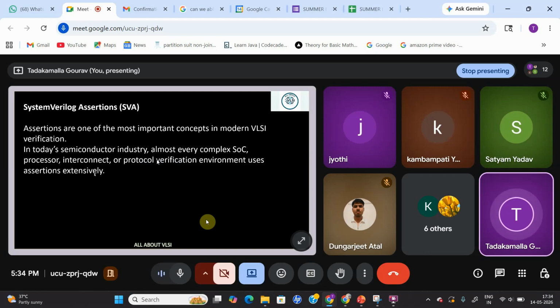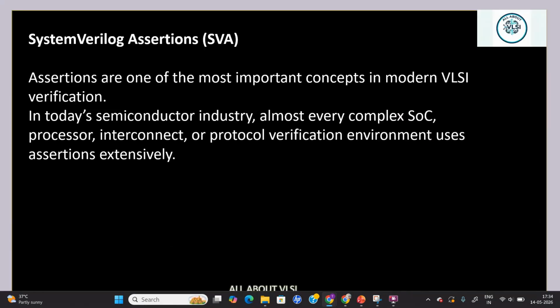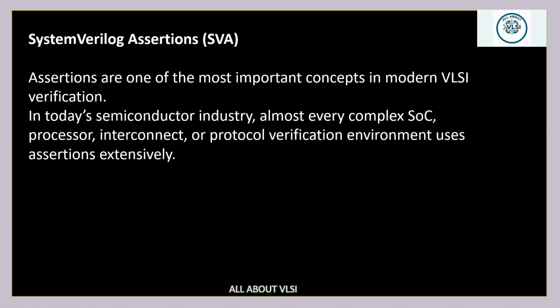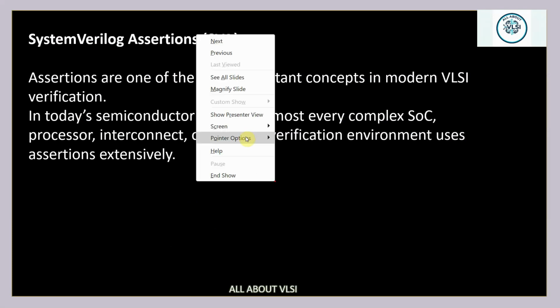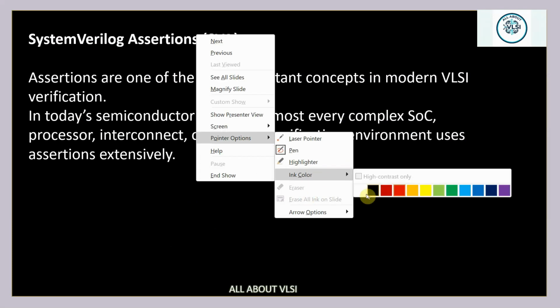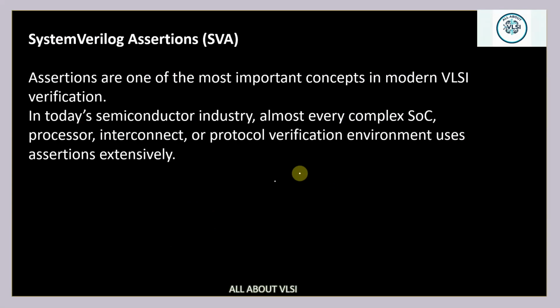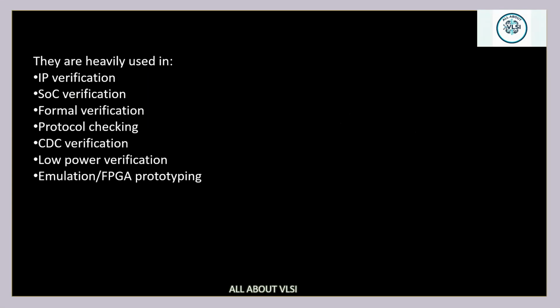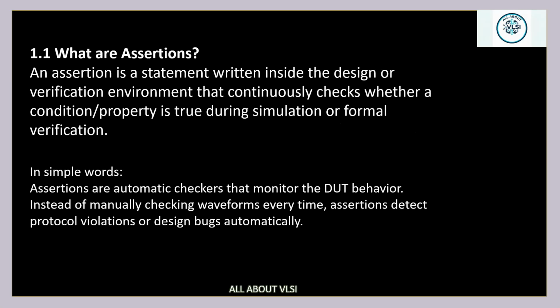Now, coming to SystemVerilog Assertions. Basically, assertions are one of the most important concepts in VLSI verification. In our semiconductor industry, almost every complex processor or interconnect uses assertions extensively. Now, what is the reason for that? Basically, they are used heavily in IP verification, SoC verification, formal verification, protocol checking, CDC verification and so on, right? So what do you mean by an assertion?